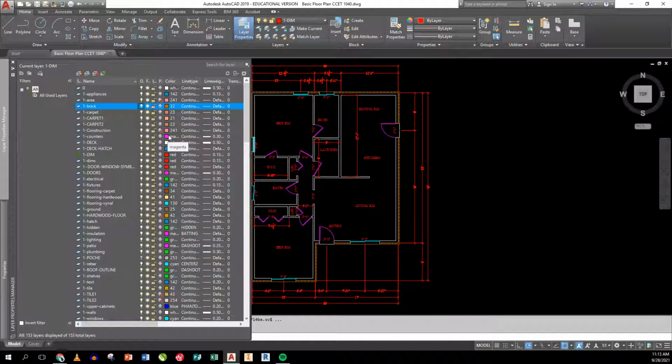I use it a lot for things like boundaries on hatches. I use it for boundaries of rooms when I'm trying to figure out floor coverings and things. Because when you do a polyline around a room, that polyline, if you list it, it will give you the area of the space it encloses. It will also give you its perimeter. Well, that makes it really easy to do calcs for things like paint and for floor coverings and determine how much you really need. So as I'm looking at these things, that's what I'm doing there.